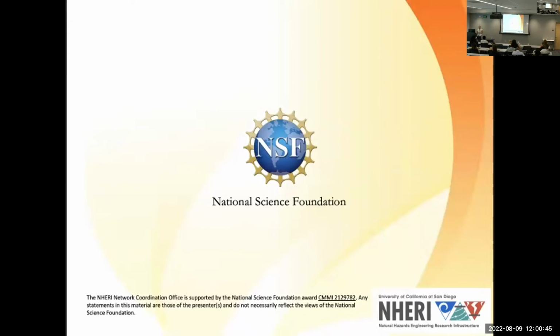So they have done research on that. This project doesn't focus on it, but I've done a little background with that. They have a 2-hour fire rating code in place already. Basically what happens is you allow this outside layer of wood to get charred, and that char becomes a protective barrier for it. So what they do in design is they'll say, okay, we need to add an extra 2 inches to all the dimensions of a column, and that is the fire rating for it.